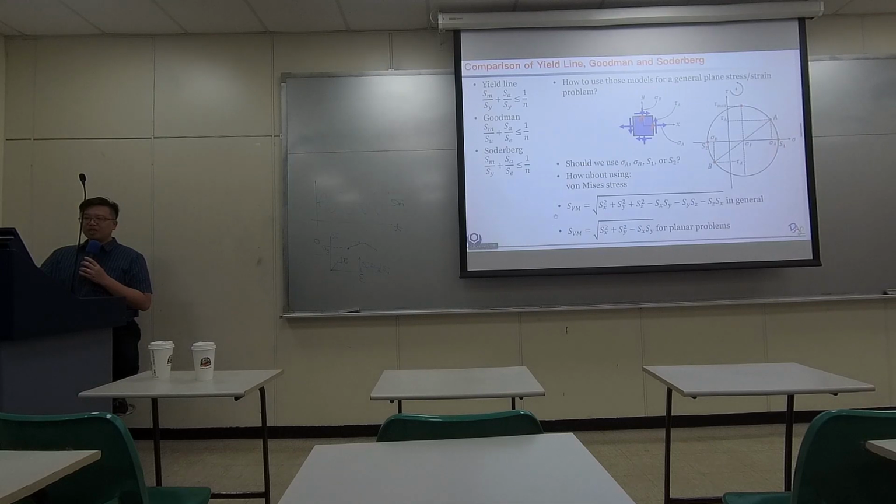So, in fact, when we use the fatigue model for the mean value of the stress or the amplitude of the stress, we actually would like to use von Mises stress for those. So in any problem that comes with shear stress, we still can consider those inside the general equation.